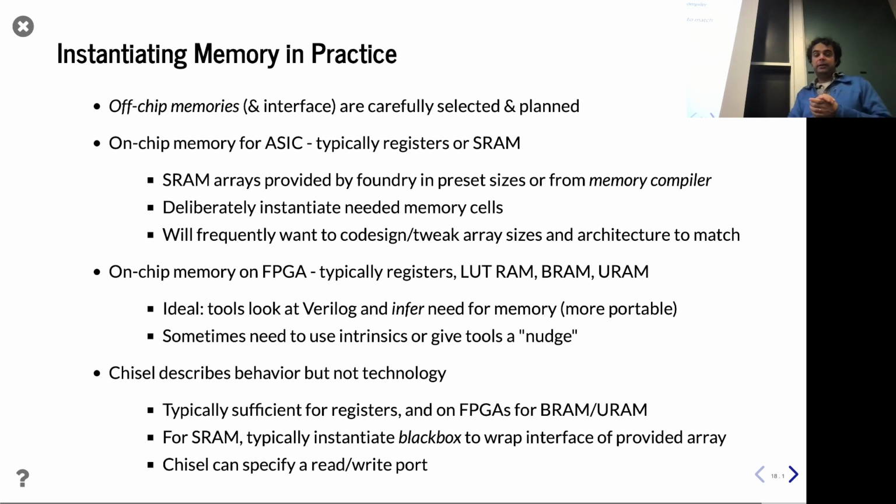Now, with regards to Chisel, what does Chisel provide? Chisel is basically a high-level functional specification. It says, hey, I have a memory, and you can say how many ports it has, how big it is, the data type, of course, and how many cycles it takes to access it. If you're doing things like FPGAs and you use a Mem, you're going to get registers. If you use a SyncReadMem, you're probably going to get BRAMs if you have 2 or fewer ports. If you have like 5 ports, you're not going to get BRAM.